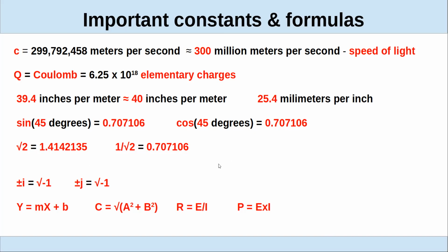Yep. Your AC power in your house. Say it's 120 volts AC. That's RMS. It's actually peak to peak several hundred volts. But RMS is a way to calculate the equivalent power if it was DC. So that 120 volts AC at your house will produce the same amount of power or heat as 120 volts DC. But it's a much higher voltage swing because